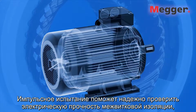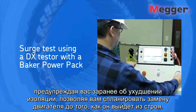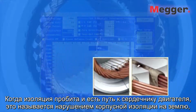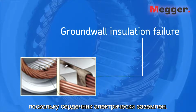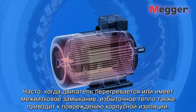The surge test can reliably find the strength of turn-to-turn insulation, giving you early warning about when the insulation is weak. When the insulation fails and there is a path to the core, it is called a ground wall insulation failure, since the stator core is at electrical ground. Oftentimes when a motor overheats or has a turn-to-turn failure, the excessive heat will cause a ground wall insulation failure also.